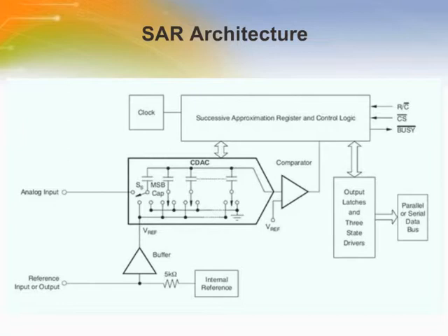Successive approximation register (SAR) converters are frequently the architecture of choice for medium resolution applications with medium sampling rates. They provide low power consumption and have a small form factor. In more recent designs, the topology of SAR AD converters uses a capacitive redistribution design approach instead of its predecessor architecture, the R2R ladder topology.